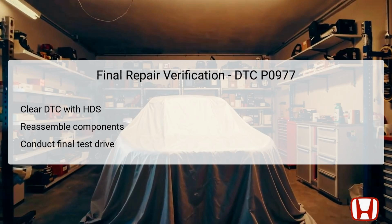Once you've resolved the issue indicated by DTC P0977, the next step is to verify the repair. Begin by clearing the DTC with the HDS again to ensure that no residual codes remain in the system. After clearing the codes, reassemble any components you might have disconnected during the diagnostic process, ensuring that all connections are secured properly.